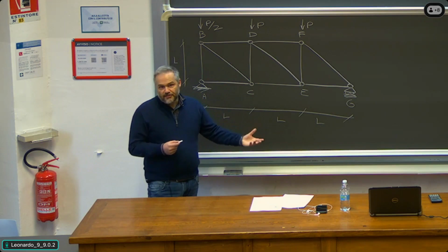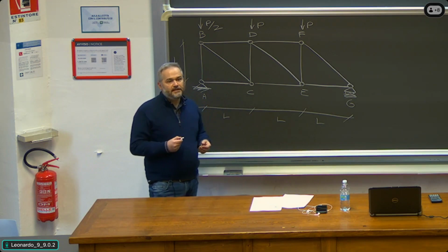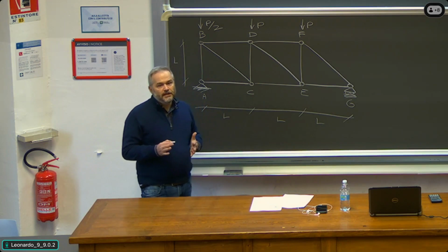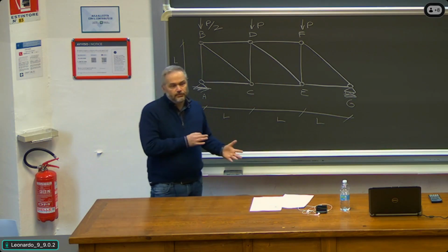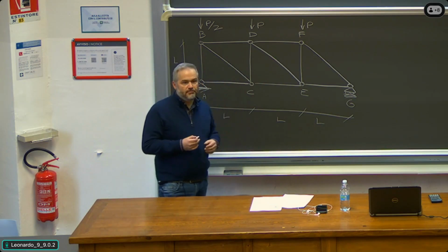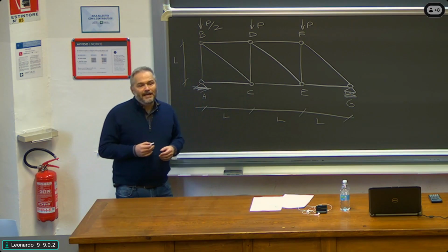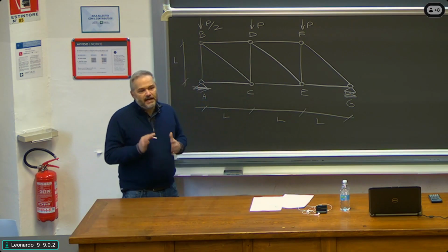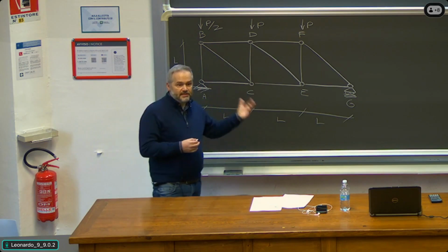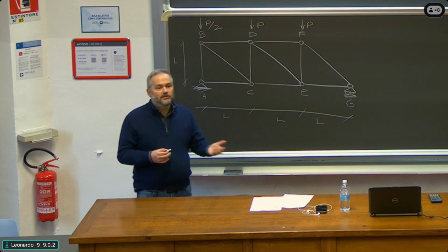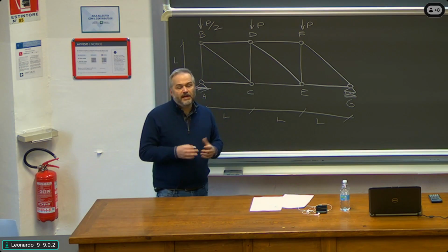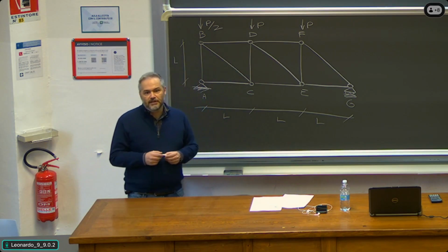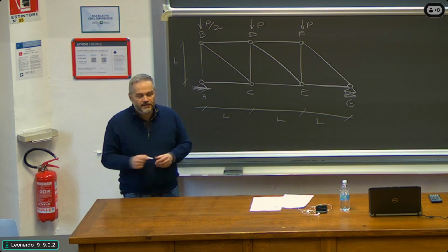But for the purpose of hand calculations, we neglect it because, first of all, it's small compared to the loads this structure typically bears, and the results are not so much affected. Besides, if you are into a design task, you don't know the dimensions of the member, so you cannot evaluate the self-weight. You simply cannot calculate it.